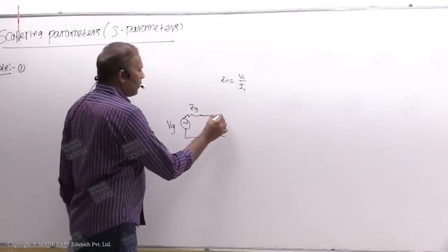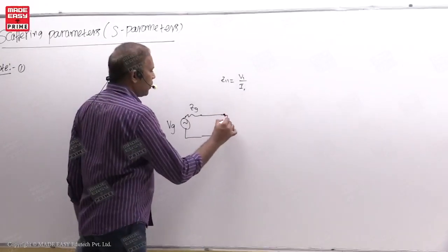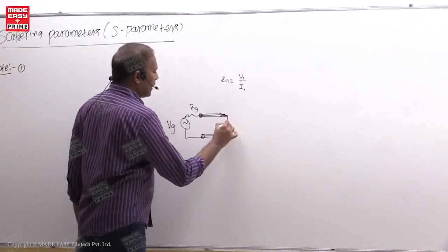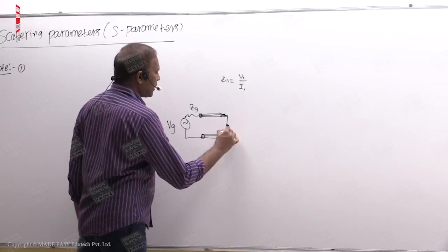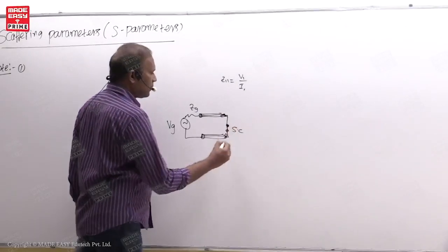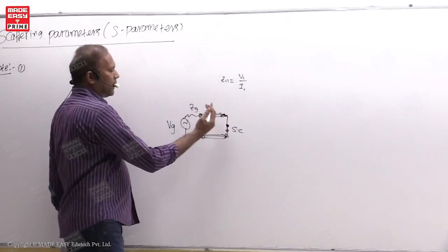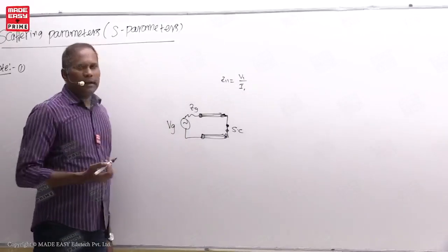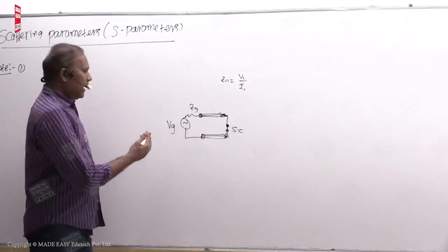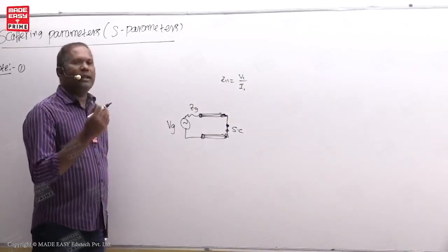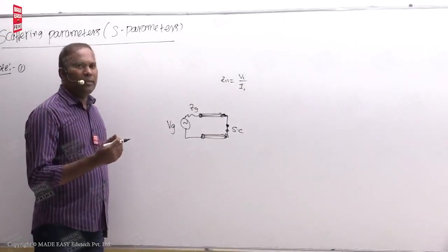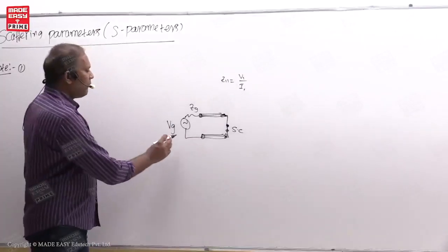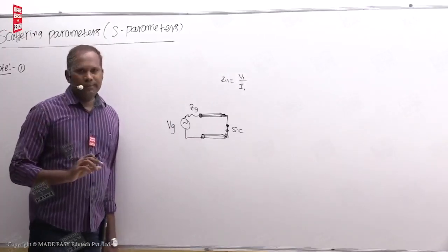Now for measurement purpose, in the transmission line, I am doing a short circuit here. Then the entire signal is reflected. Then when it enters the tunnel diode, it starts giving a different frequency, that is called frequency instability. Sometimes it may burn off. That is why the device goes to unstable mode.